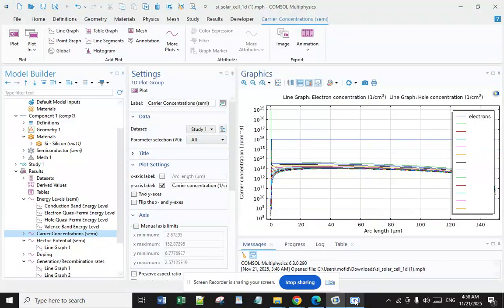This n-type silicon wafer is created by uniform bulk n-doping, with doping from the front surface and uniform bulk doping easily accounted for by using a geometric doping model feature and an analytic doping model feature, respectively. We use a boundary selection for the doping profile node to define the surface and add two metal contact features to specify the electrical connection between the front and back surfaces.